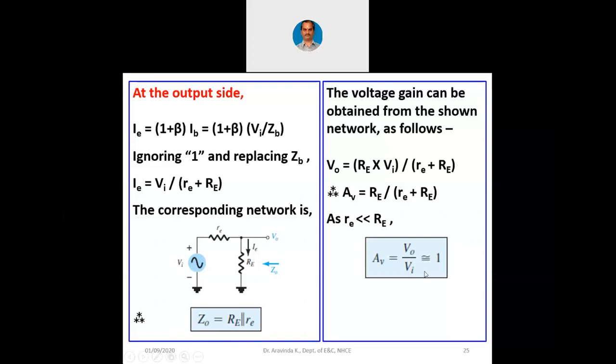So what do we have to do? For voltage gain, we will use common emitter, and then later on, we will have one more common collector stage. The common collector will have low output impedance, which means we get voltage gain and we get low output impedance by connecting two circuits in cascade or in series. Then we can call it a multi-stage amplifier. That is how we actually get multi-stage amplifiers.